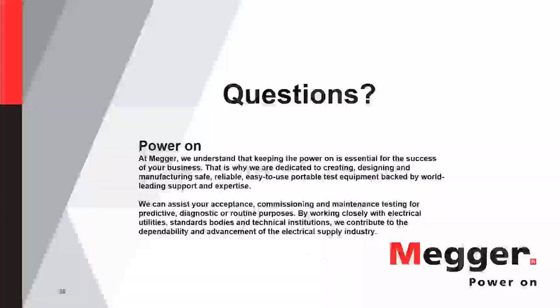It's generally whatever's easiest to connect and what information you have. If the manufacturer recommends one, go with theirs. If they don't, then go with whatever's easiest for you to connect to. Normally it seems like the dead tank side is more often using linear transducers and the live tanks are using rotary, but there are exceptions to that as well. So you really just have to evaluate it. But it doesn't matter as long as you're making a connection and converting that value correctly. All right, next question.